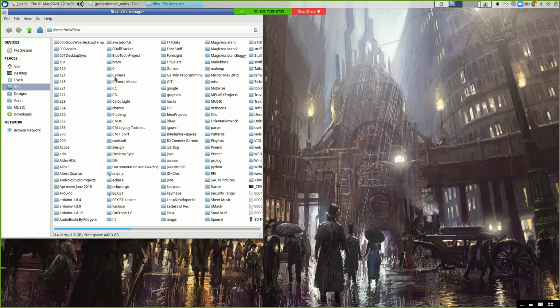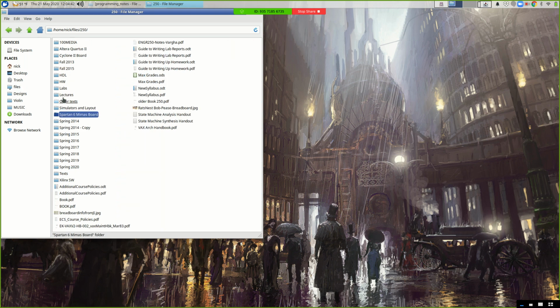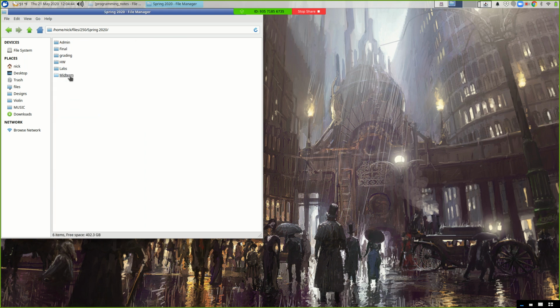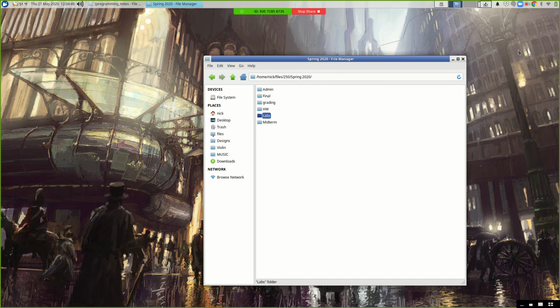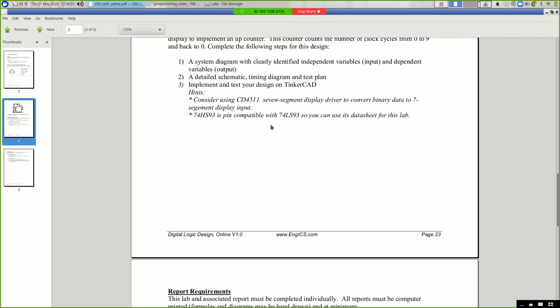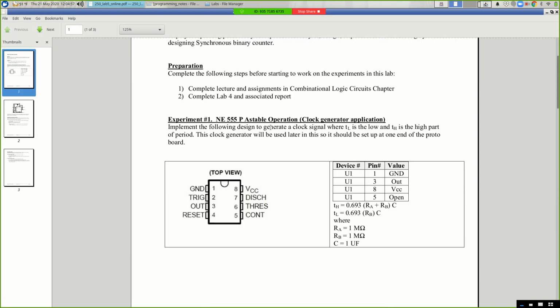So for Lab 5, I sent you an email about it. I can't get my circuit to reset back to 0. Right. I put it through an AND gate and then set it to the 2 reset inputs on, I can't remember what the chip is, I think it's the 93. But it sets it to 8 after it gets to 9 and then it stays there.